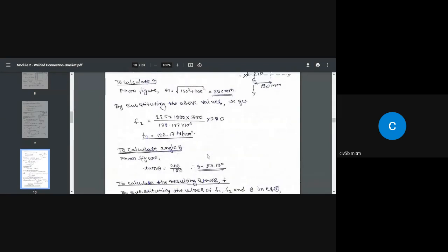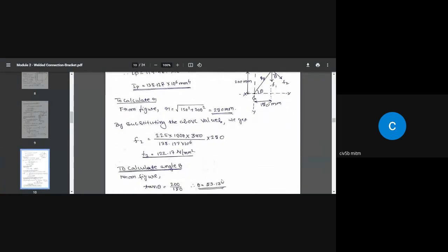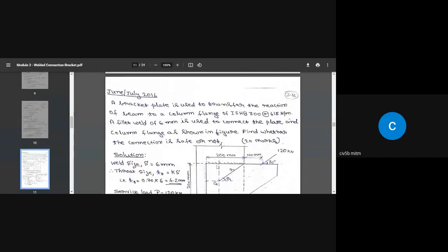So if you correct this mistake, which I forgot to multiply this value by 2, once you correct this mistake, I think this value will go down further. Okay, so that is, F value will go down further. So this completes the problem. Therefore, the provided welded joint is safe. You can declare that with that sentence, then you can end.